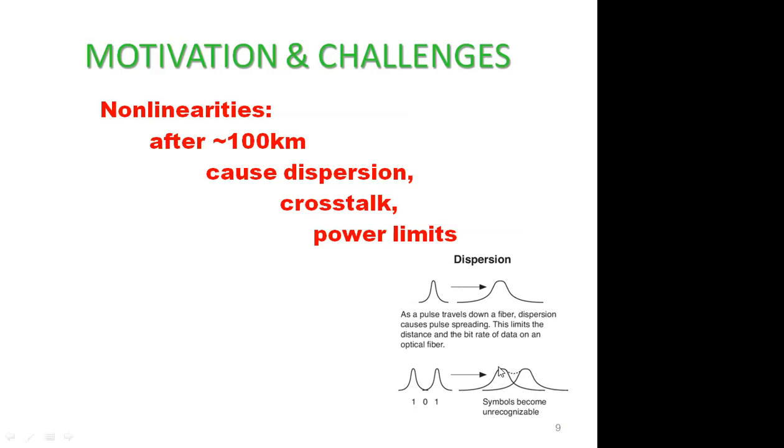If you look at this area, there is interference, interference of one pulse with another pulse. And this leads to crosstalk. Followed this? This is one of the problems in single mode fiber. But what is the phenomenon by which there is dispersion? Why is this happening? Why is the pulse width increasing?